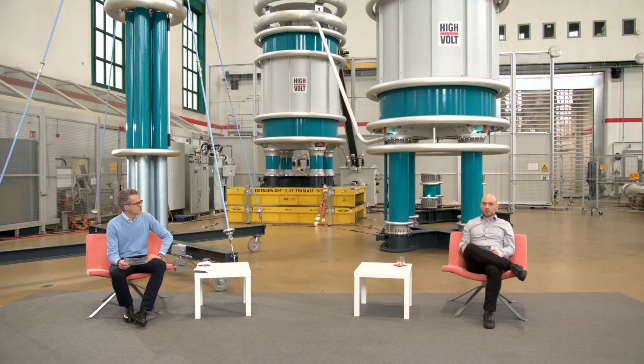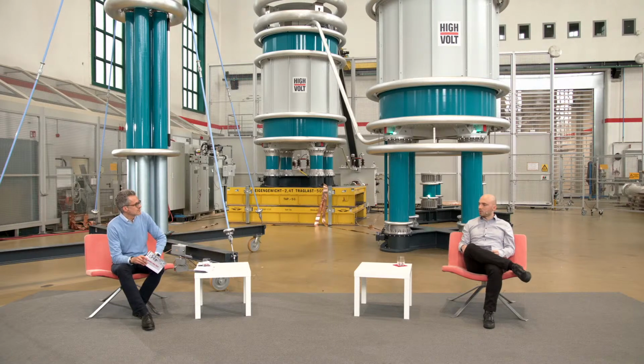So it's more or less a jump from operating voltage to 0. And for this, we don't need to measure every link box. So in the case of a German corridor project, it would be sufficient to install this location technique in all of the transition stations and to equip every link box with a monitoring system for PD. And of course, the final product will combine those features in one.